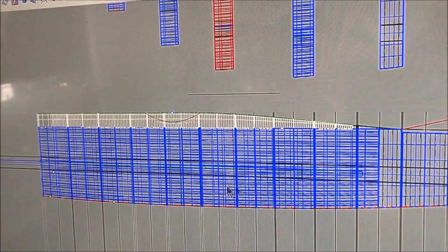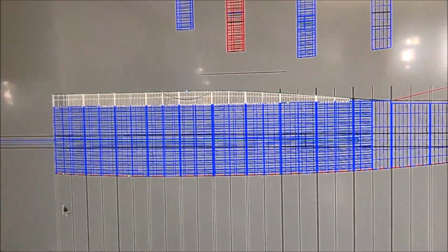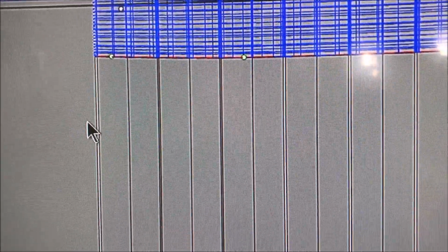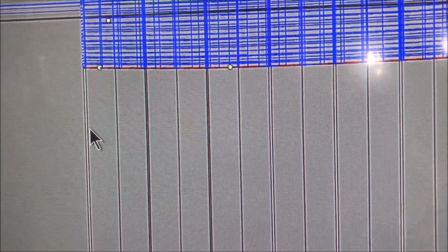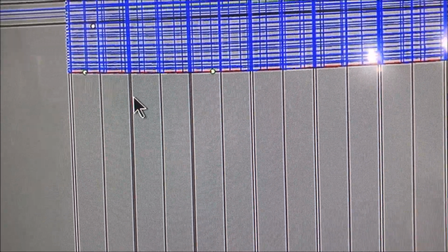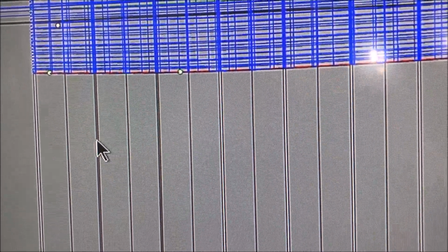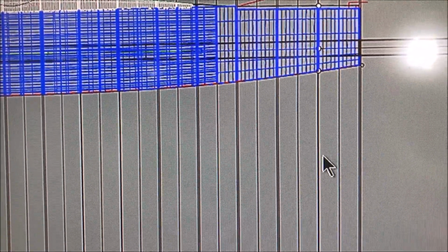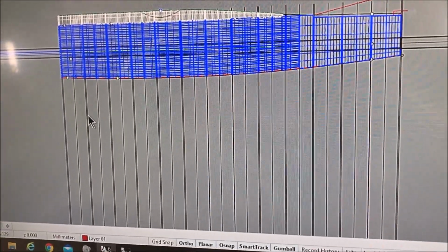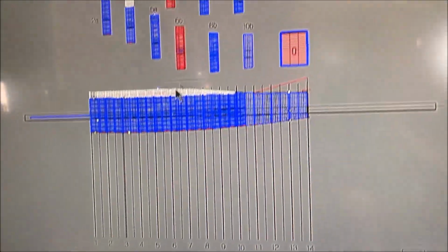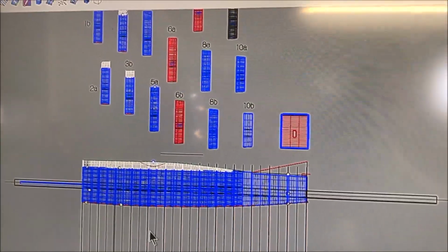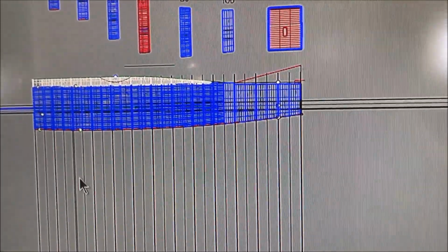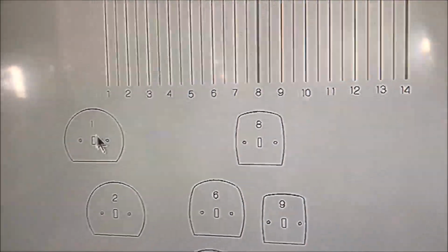We've got our fuselage. Each one of these slices is 50mm apart. So we start off with a slice of 3mm MDF and then 2 bits of foam. Another bit of 3mm MDF, 2 bits of foam. So right the way down the fuselage, I've chopped it all up into MDF, foam, foam, MDF, foam, foam. And then just like we just did, you can pull out shapes. So I pulled out former 1, 2, 3 down here. So these are the MDF shapes.